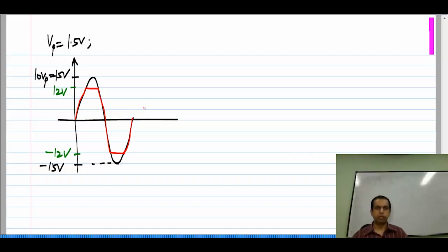Okay. So, whenever you use an op amp, you have to also make sure that all the relevant voltage levels of the op amp, the individual input voltages V1 and V2 and the output voltage V naught are within the specified limits. In absence of information about a particular op amp, you assume that the limits are equal to the supply voltages. Okay. Now, I won't discuss this in further detail.